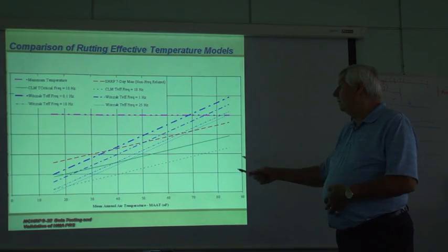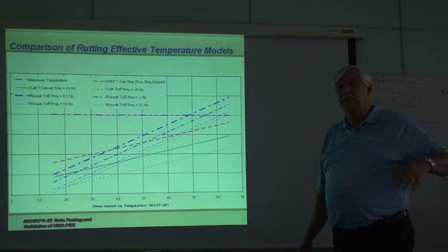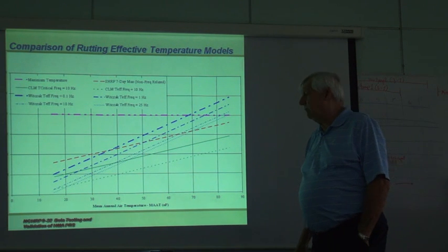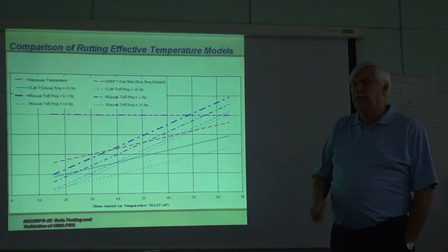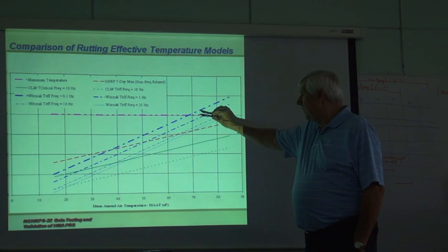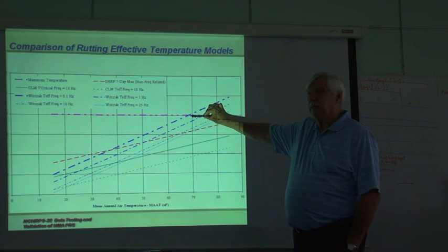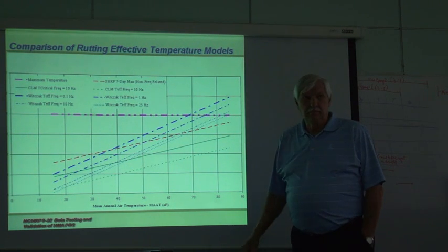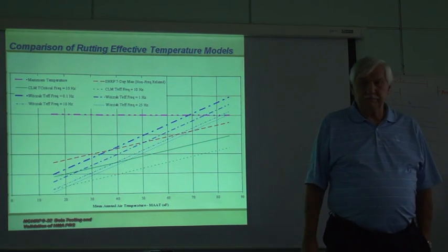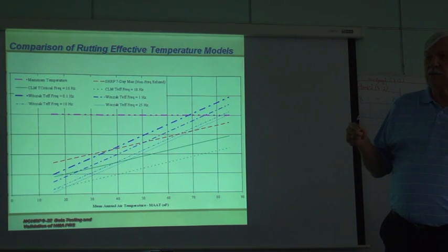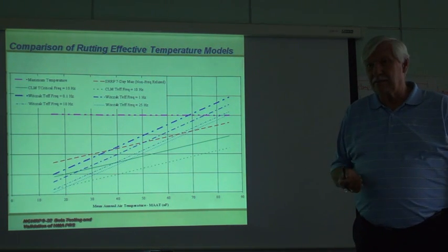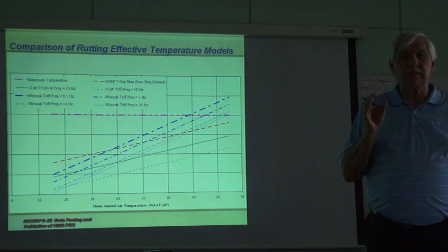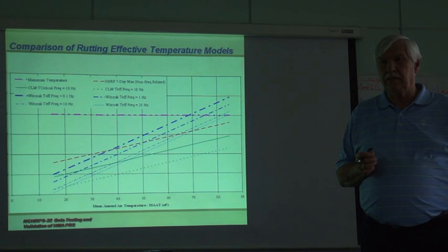Okay, if you look at what we have, typical results, let's say for rutting. We've had effective temperature results for rutting for many, 70, 80 years. The first one I'll call your attention to is right here. What's the temperature? It's 140 degrees. Where did that come from? Well, when Bruce Marshall developed the Marshall stability test, he said that the critical temperature to evaluate this is 140 degrees.